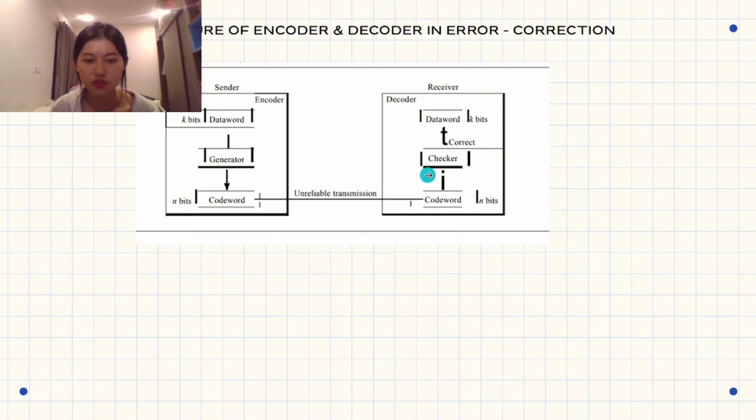It goes to the Hamming checker, the parity checker, which takes the data bits after transmission and creates 4 new parity bits, and then XORs the new parity bits with the old parity bits together to know where the error happened, then corrects it and goes to the output.